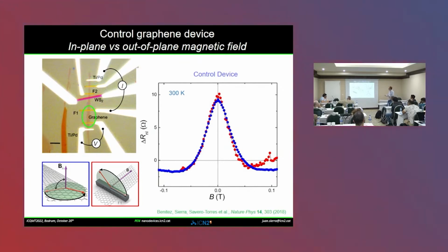So in our device, unfortunately this picture didn't show you a real device. Now you have to believe me. We attach metal electrodes on the transition metal dichalcogenide to characterize it by itself. What we did is we inject a current, we apply a voltage through this interface, and we measure the current that was flowing from the TMD to the graphene. Okay? So these are the IV characteristics that we measure.